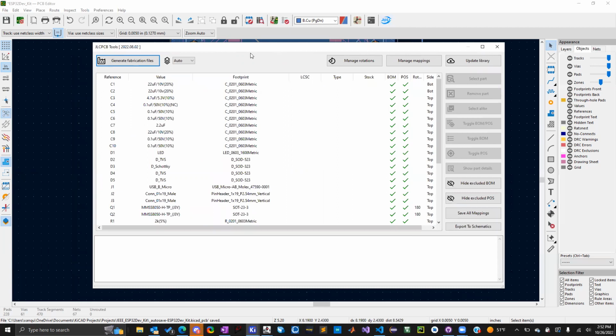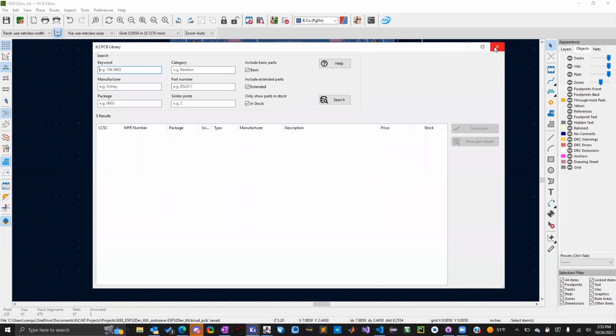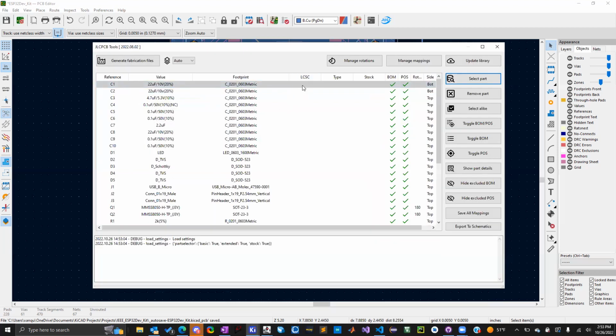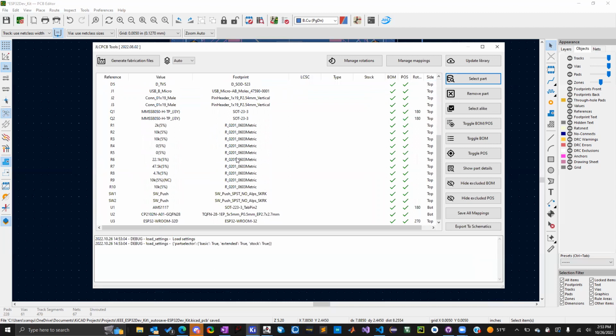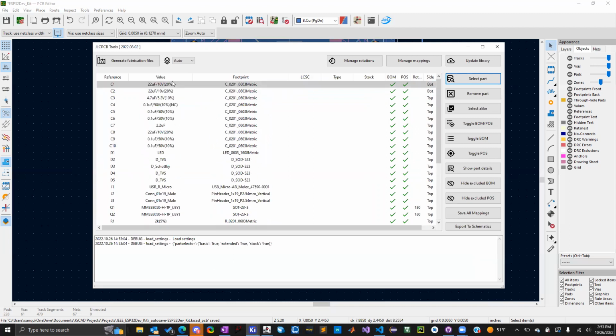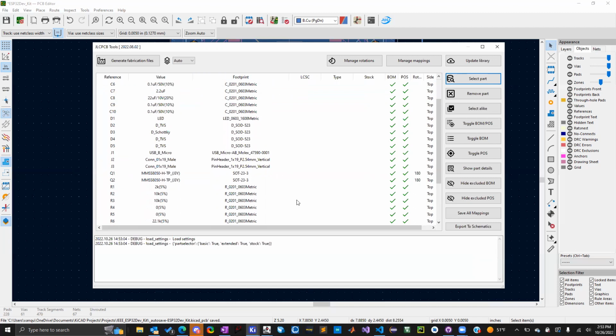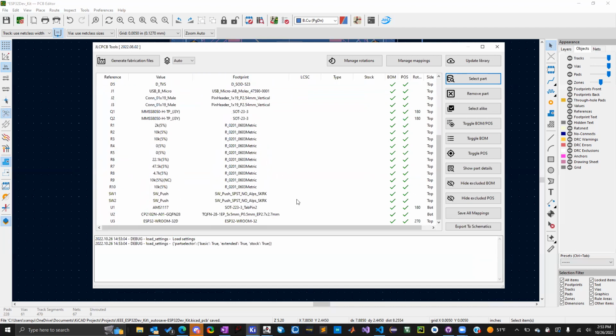It's okay if you don't. You can use a different manufacturer and you can use KiCad's thing. But this is convenient because I can pick parts directly that are available from LCSC. So that's what I'm going to do, and you guys don't have to do this, so don't worry about it. I'm going to pick all these components out, create a bill of materials, and ship it to JLC PCB. They'll make our boards and throw these components on with the BOM that I gave them, and you'll have a dev kit.